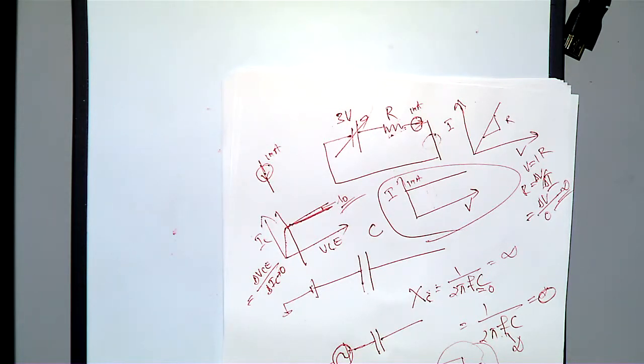And then you got R pi, and then from here you got to ground, and then between collector and the emitter you got the current source gm v pi, and then from here you are getting output, see RC. After RC you got this DC voltage that is not changing with respect to time, so that we ground it. That's the reason we grounded. And then this is your V out. V out is between collector and the emitter, between these two grounds.